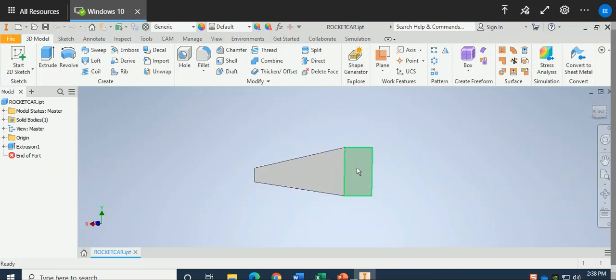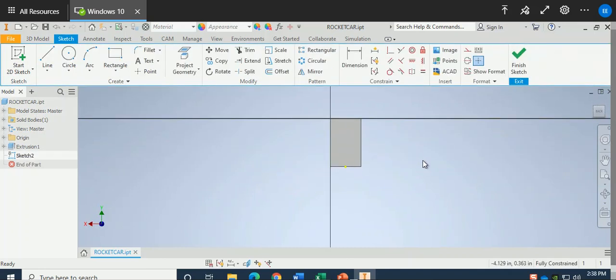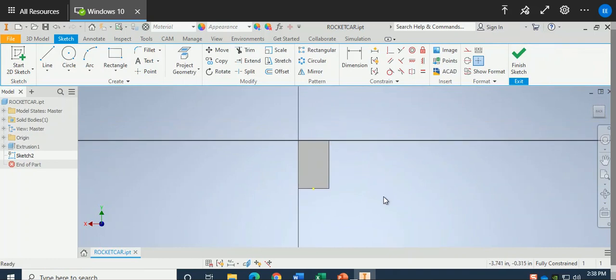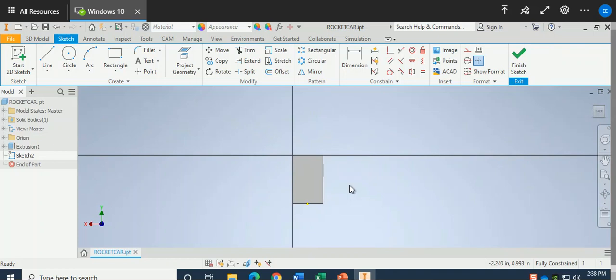So I'm selecting the face, the plane first. Click. As soon as I click on it, the computer knows what I want to do, so it gives a bunch of options. The last option is actually my first choice, which is Create Sketch. So click on Create Sketch, ta-da, and I have this in front of me. So now I'm ready to draw a circle, first of all.